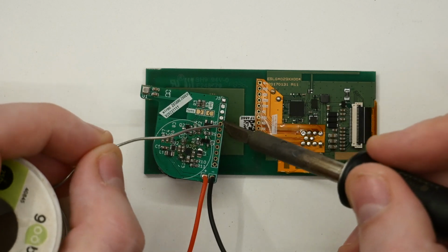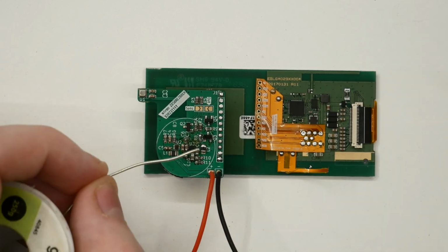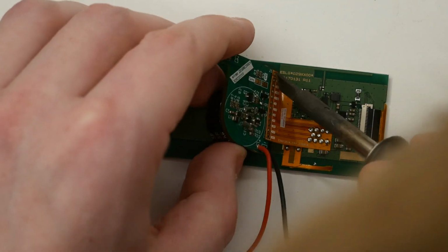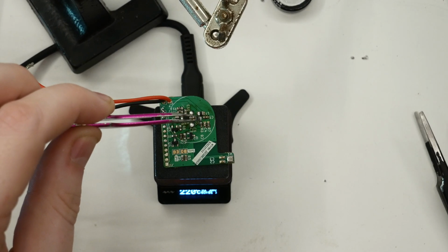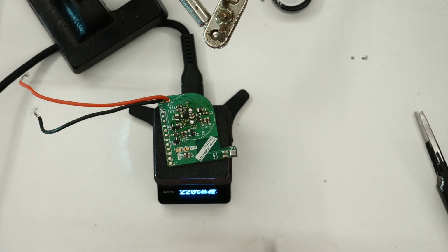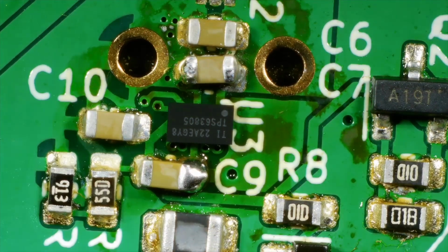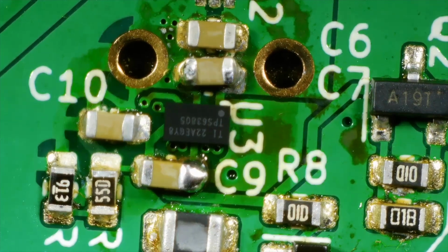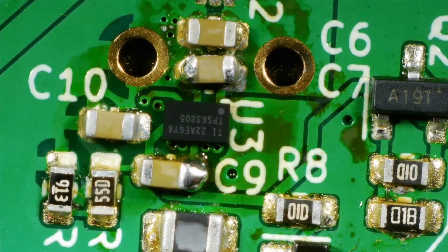I then decided to connect the display using one of the flex PCBs. During the process I somehow damaged the boost converter because the PCB was heating up again. While replacing the boost converter, I bumped the other BGA buck boost converter, which resulted in the pads shorting again. I then tried to replace it again and finally gave up because the whole circuit did not work well from the start. So what did I learn?